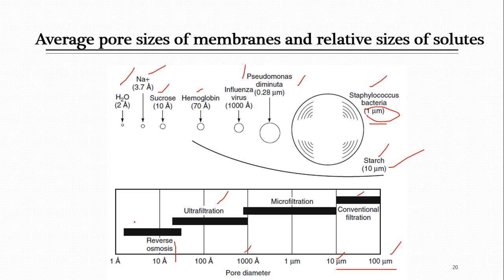When you look at various books, most of the time reverse osmosis membranes are referred to as dense membranes, which don't have any pores, so they can separate all the stuff. But the nanofiltration membrane size was given as 1 angstrom up to 10 angstrom, so they can also be used for removal of small size molecules.